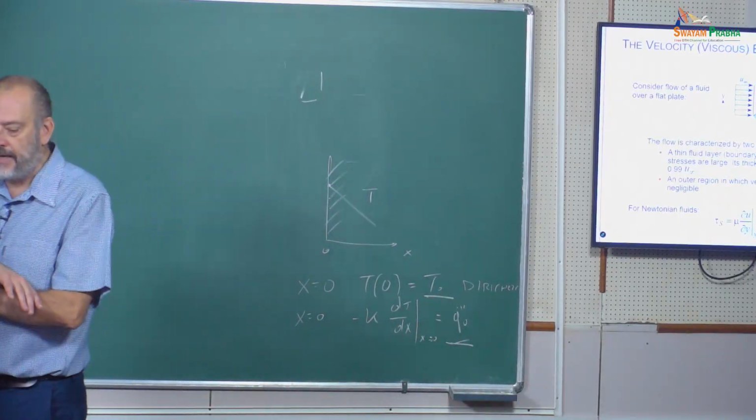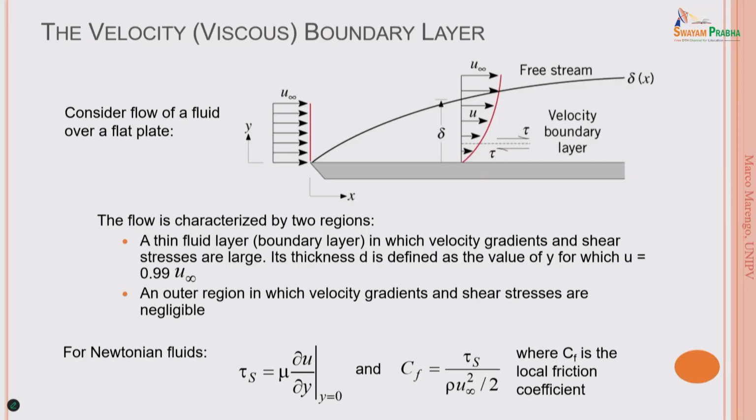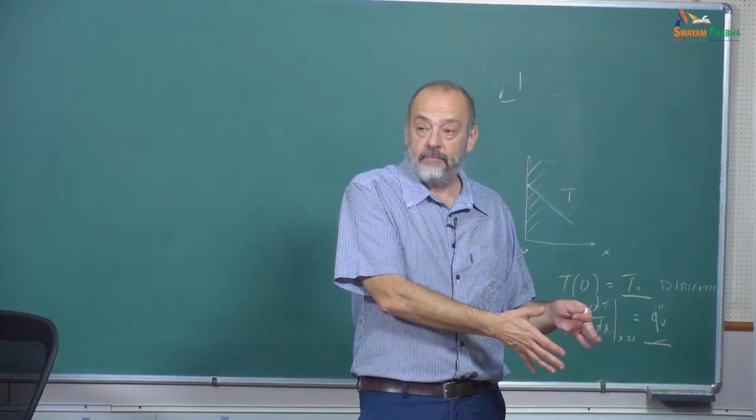At the end, we have a kind of curve on a profile, on a surface, that says how thick the boundary layer is. What is inside the boundary layer? Inside the boundary layer, we cannot neglect the viscous forces. This means that inside the boundary layer, we have a change of the velocity due to the fact that we are already feeling the presence of the wall.